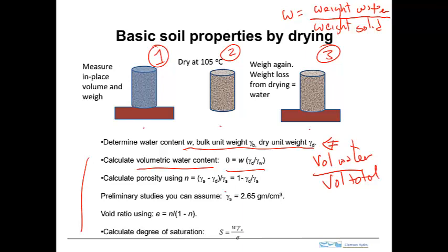And here's the calculation for porosity in terms of these unit weights. One thing that I should point out is that typically what's done is to use just an estimate for the unit weight of the solids, and this is done by just assuming that the mineralogy is either quartz or clays, and using this as an approximate estimate for the unit weight of the solids.